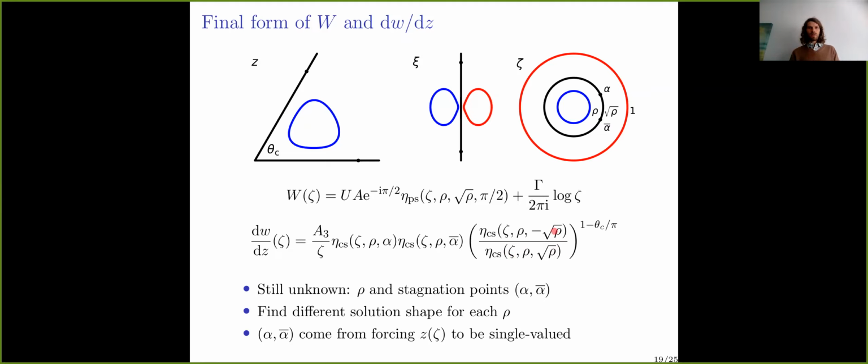But we don't have that here, so we have these extra terms, and these are going to be matching behaviors of the point vortex with the arbitrary angle corner. So you see this power in here, and we basically are just recovering the point vortex solution as we go close to the corner, far away. Over here, that means close to 0, close to infinity. We expect and match and enforce that it looks like the point vortex solution to get these constants.